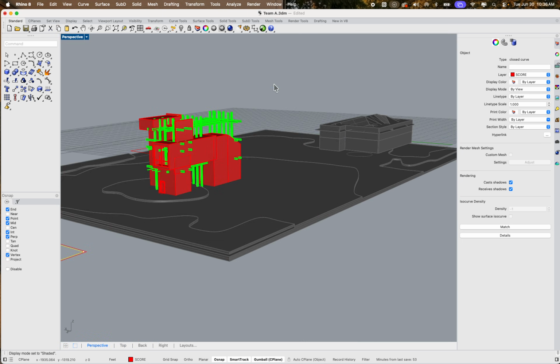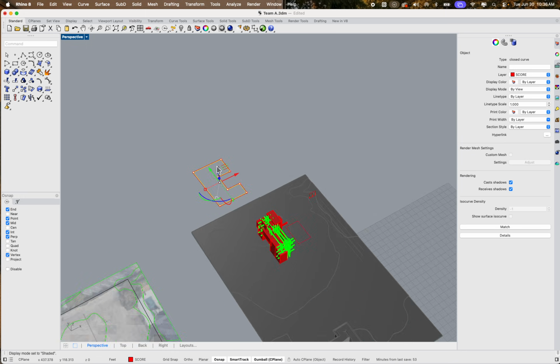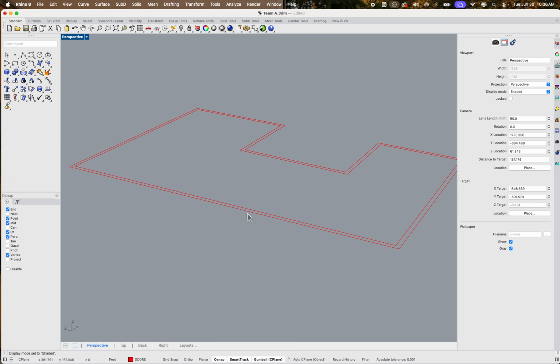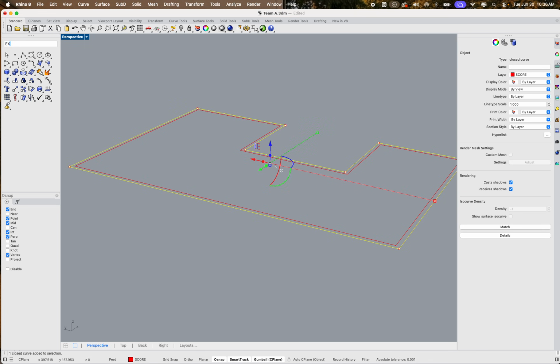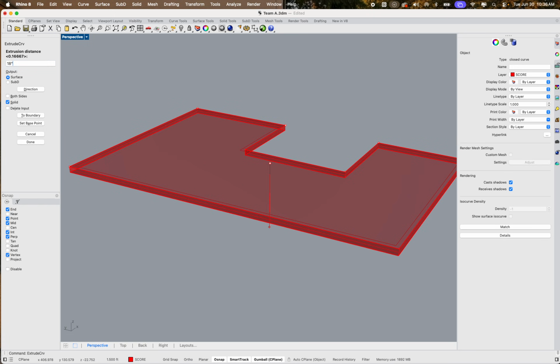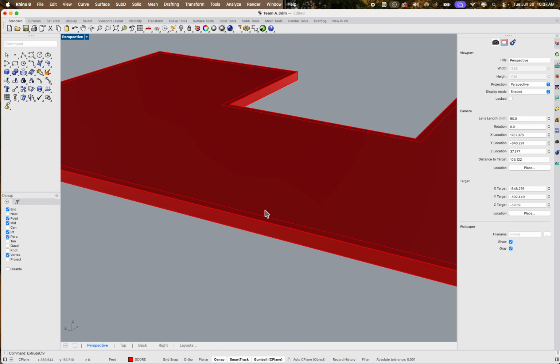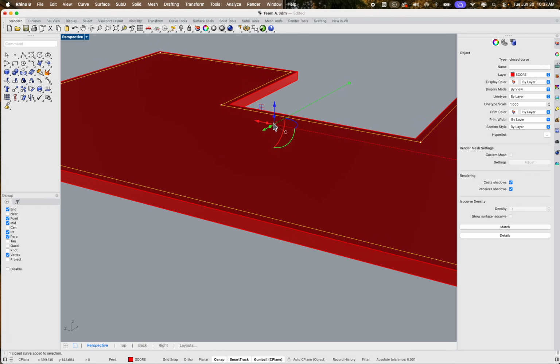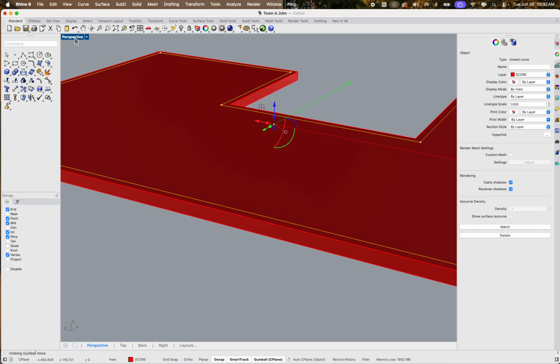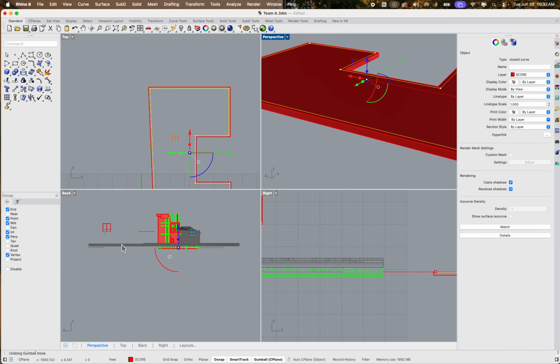Let's go to shaded. Let's find that piece. You know, it's probably because I messed with my C-plane. Now that I think about it, all the weirdness. Typical foundation, about 18 inches thick. So we'll go with something like that. Good thing I have that offset piece, because basically I can move it in, maybe even down 6 inches, you know, for the thickness of that floor.